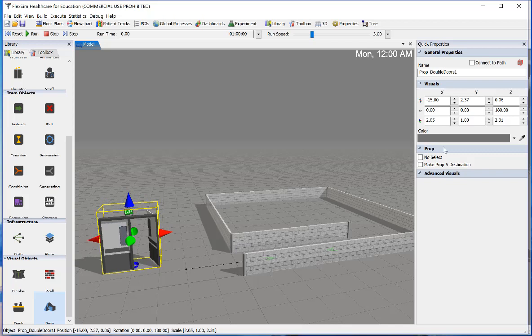But one of the things that you may not be able to do easily is rotate this. So that's something that you may want to do on this side, because here, this represents the rotation in X direction, Y direction, or Z direction. So let's say in the Y direction, I put 90 degrees rotation. See, it actually got flipped over, which is a very weird look, as you can tell. So I'm just going to Control Z and make this 0 again.